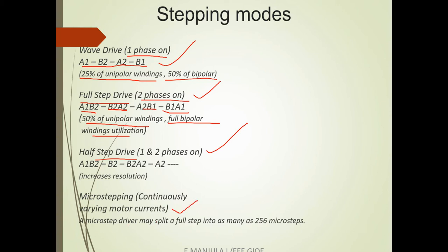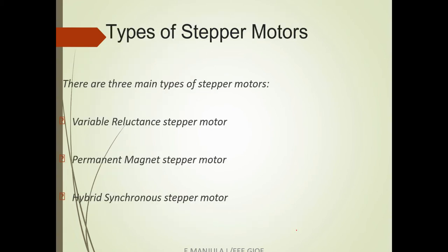And micro stepping, the last one, continuously varies the motor currents. So the micro step mode drivers may split a full step into as many as 256 microsteps.